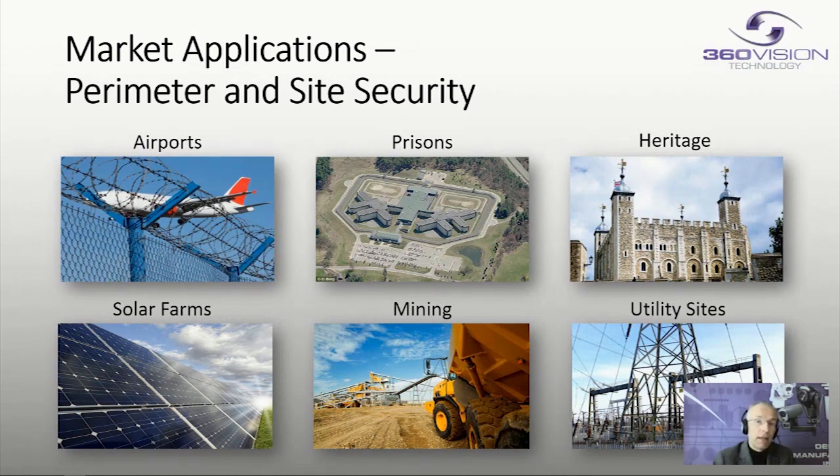Whereas the radar, if it's in 360-degree mode, will be able to look into sight and away from sight as well. Now, that can be really crucial, particularly in having early warning that someone is approaching site. If the site is a utility site, for example, and some of those are essentially in remote locations, no one should be really going near them. So having a system that will give indication when someone has come within a few hundred meters of a site